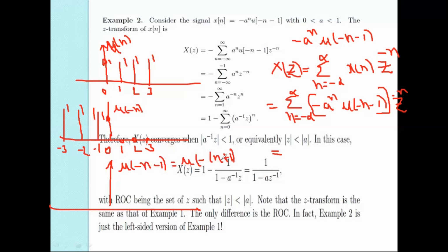Plus means an advanced function, but you have to do it for the folded function, so one sample moves towards the left-hand side. Got it, my dear students? If you add for the folded function, it moves towards the right-hand side, but the subtraction in the folded function means the left-hand side. Minus means the delay. For mu of n, you shift towards the right side; for mu of n plus 1, you shift towards the left side. But for the folded function, it is the reverse operation.